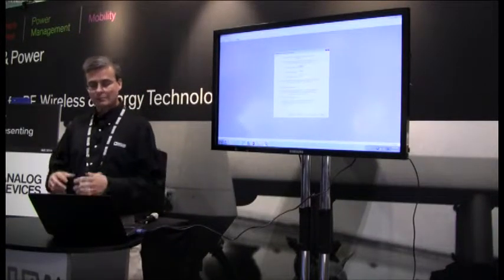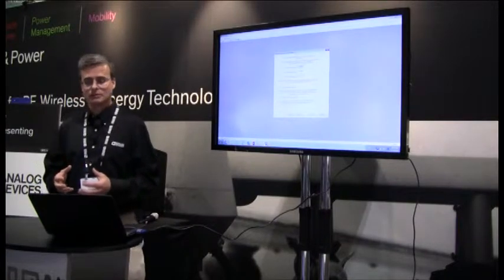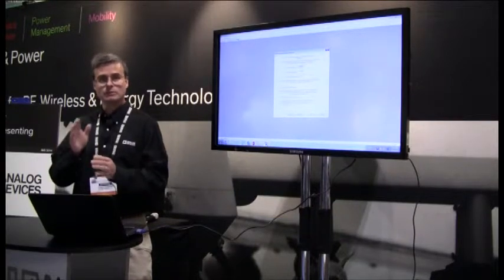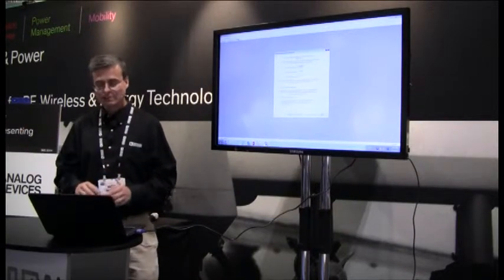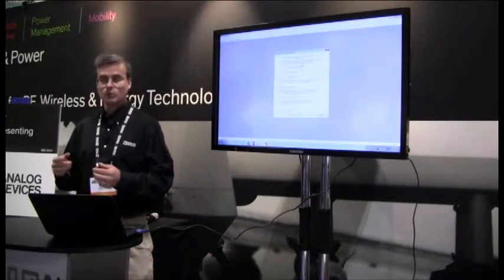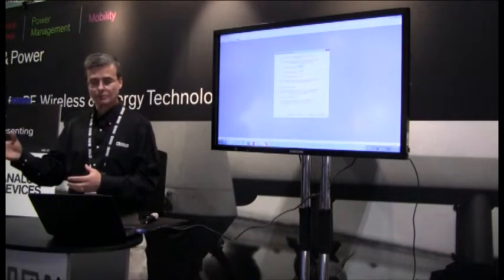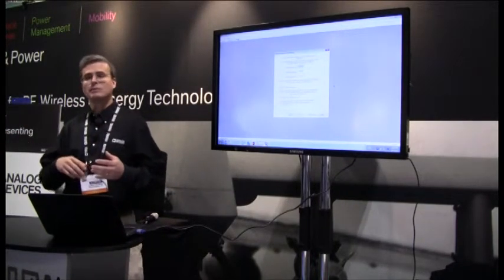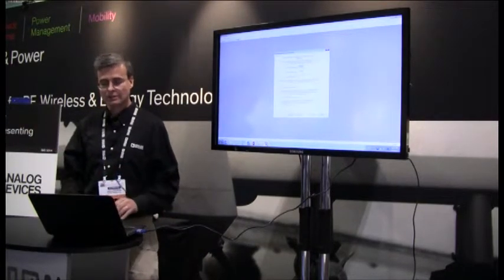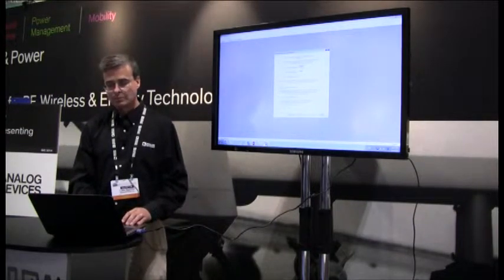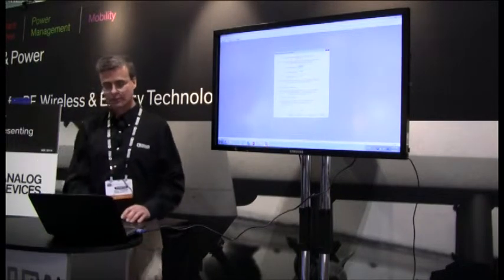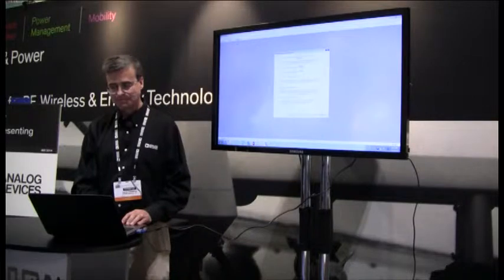Next, since I'm sweeping, it gives me the choice to be able to choose the minimum frequency, the maximum frequency, and the phase detector frequency, which would determine the steps that I'm able to take in between that. You also have the ability to choose whether you use an external prescaler, so you would be able to use this at a higher frequency than what you would normally be able to do by using a prescaler. We will also be able to use a multiplier, so you can actually multiply up and it'll do that calculation.